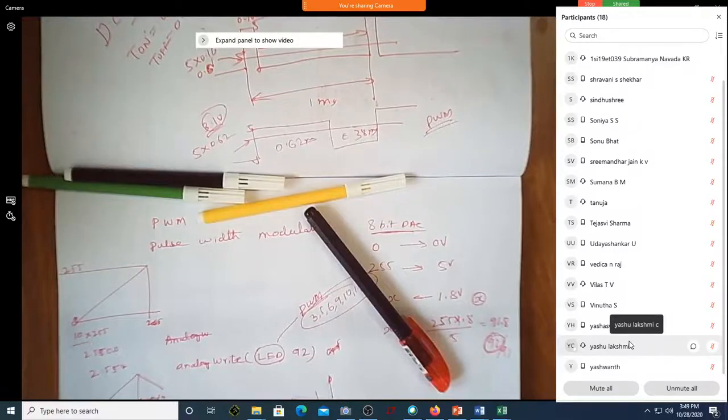There will be some small program running so that once you enter that function, because of the parameter you passed, 100, 1000 or whatever number, that function keeps executing for the desired amount of time the user specified. Then afterwards it comes out and proceeds. Those are all predefined functions in Arduino.